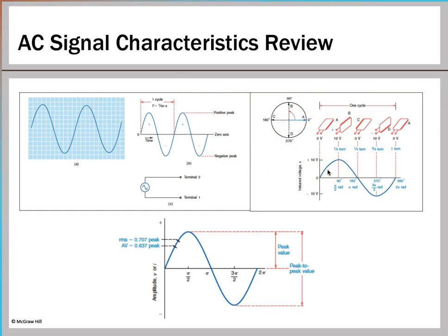And there is a quick question for you all. What is the easiest measurement to make: a voltage, a current, or a resistance? Voltage is easier to measure compared to the other two, because in voltage measurement you just leave the equipment power on and place the voltmeter leads across two points in the circuit to make a measurement.